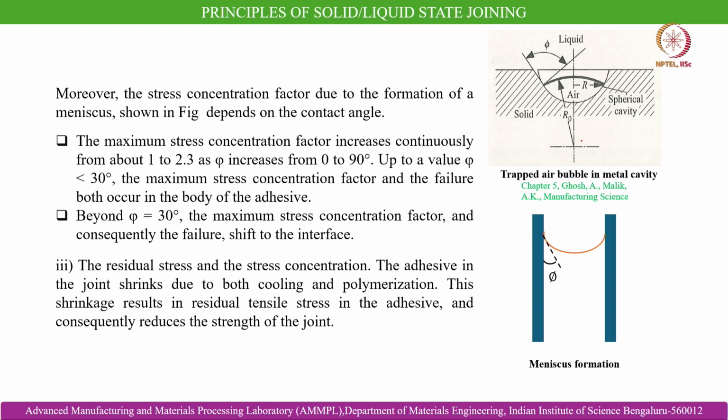If phi is less than 30 degrees, the maximum stress concentration factor and the failure both occur in the body of the adhesive, and beyond phi equal to 30 degrees, the maximum stress concentration factor and consequently the failure shift to the interface. This is what the concept of meniscus formation shows in this schematic.